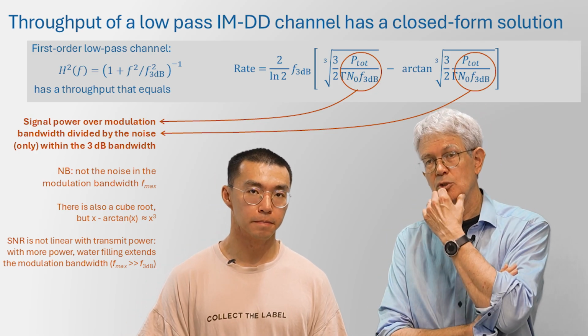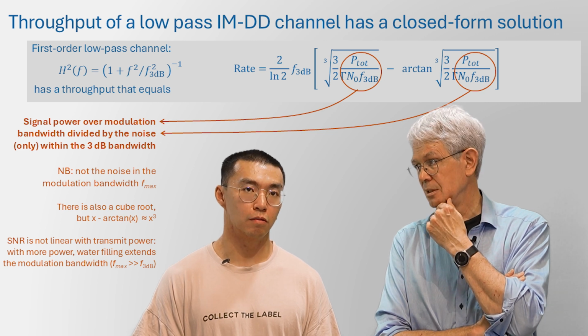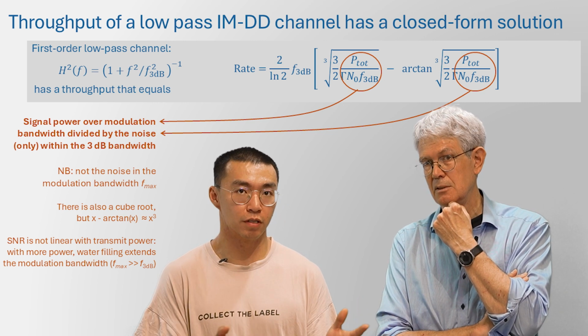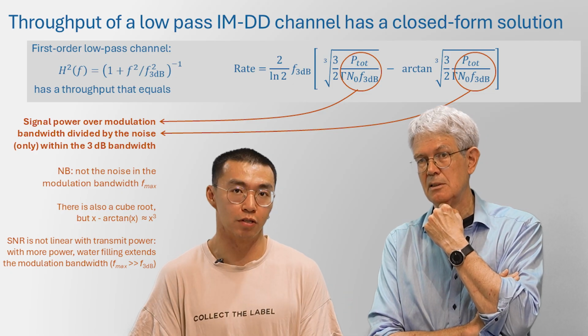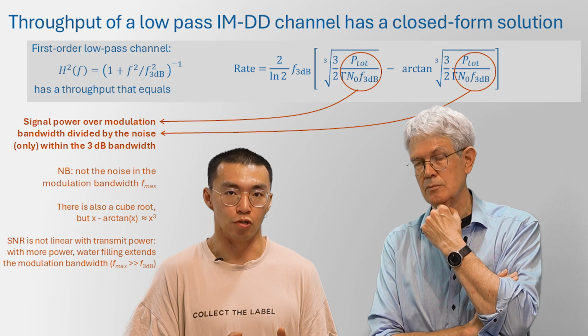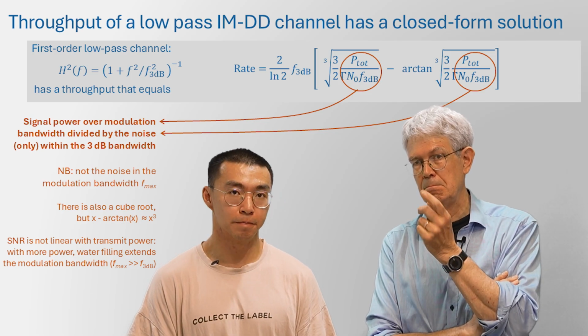And also signal to noise ratio is not a constant. Especially for different subcarriers, the signal to noise ratio varies from subcarrier to subcarrier. So it's not really the best choice to use SNR for the whole channel in this scenario.